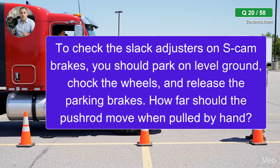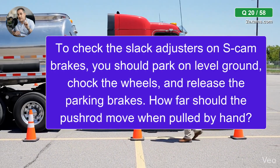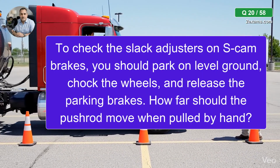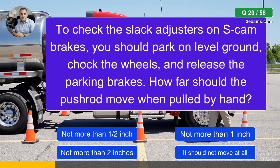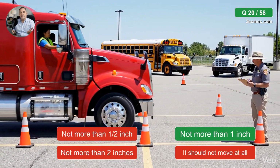To check the slack adjusters on S-cam brakes, you should park on level ground, chock the wheels, and release the parking brakes. How far should the push rod move when pulled by hand? The correct answer is, not more than 1 inch.